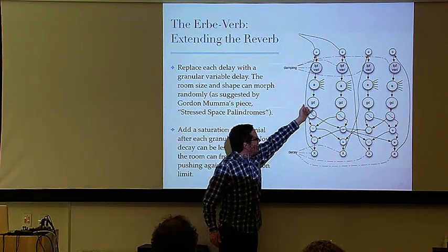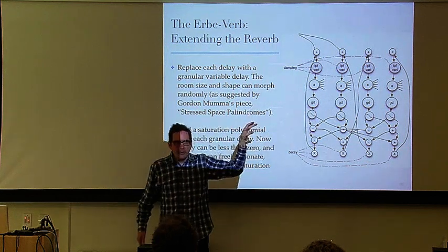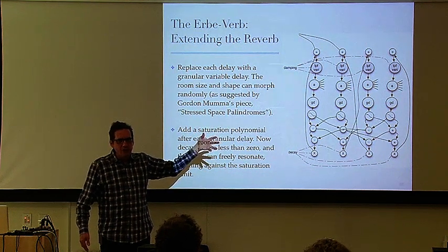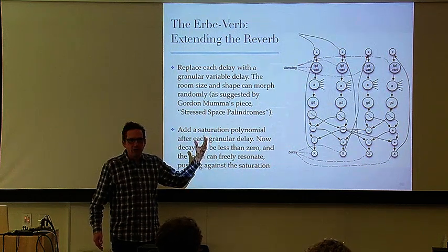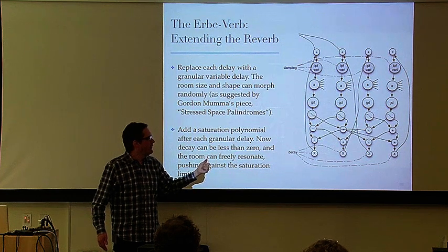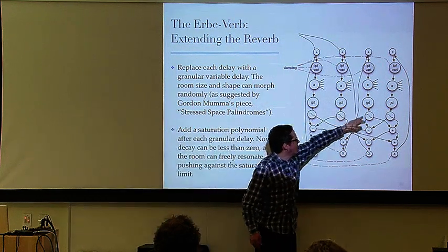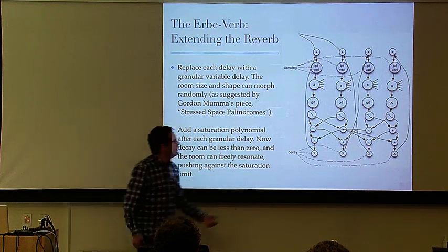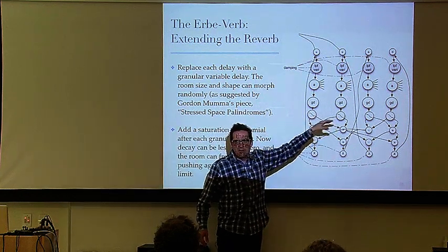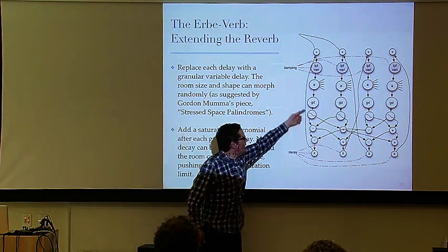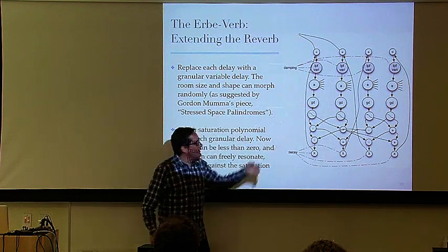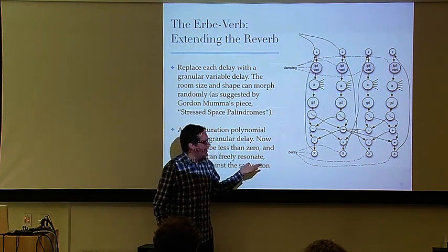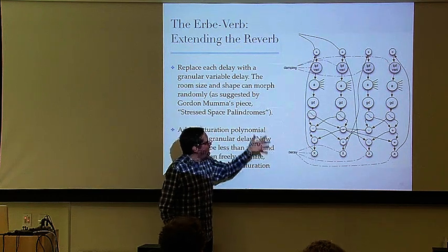So now that I'm doing this, if you've done any sort of stochastic process like this, especially in a feedback loop, you'll see now that gain is somewhat unpredictable. Yes, you're throwing a random element in there. You can figure it out on the average, but if you're doing things slowly, you now have a real source of feedback. So the next thing to put in here are sigmoid functions. You need to have some sort of clipping protection in there, or you need clipping protection plus short time limiting, something like that to allow you to bring the gain up and not have things explode. Or have things explode, but make them sound frightening rather than terrifying. I don't know. You want to have some control over the process.